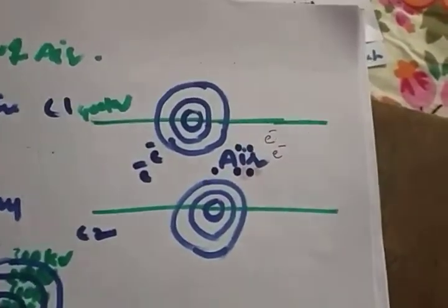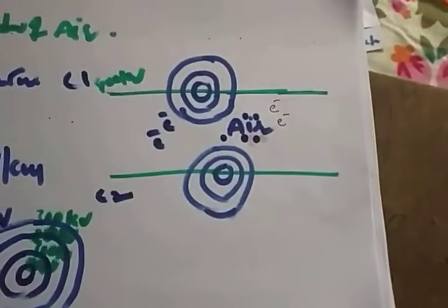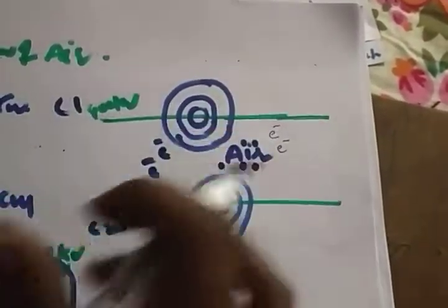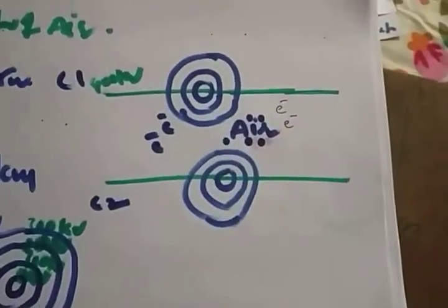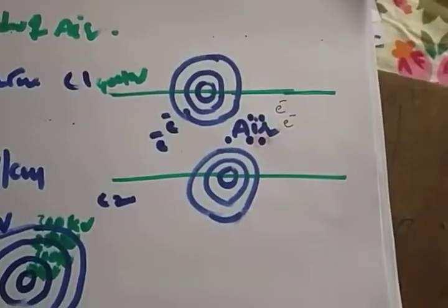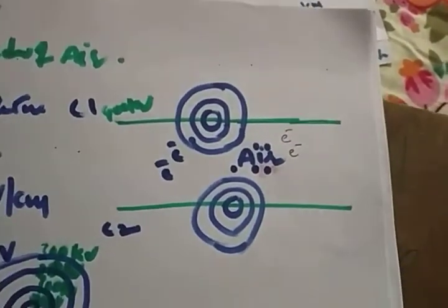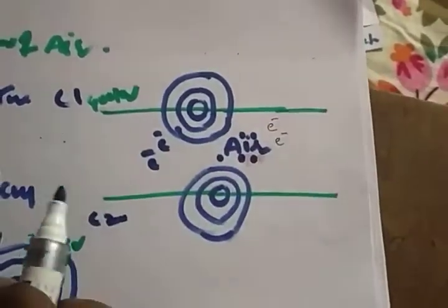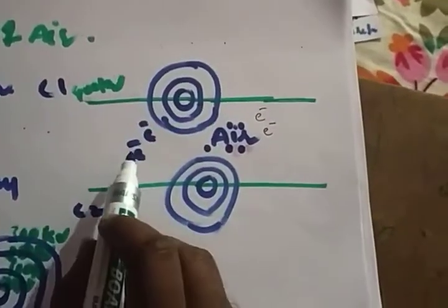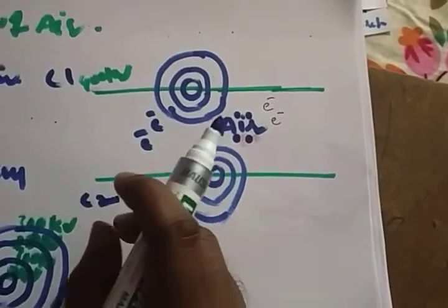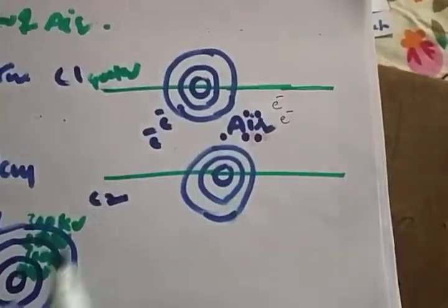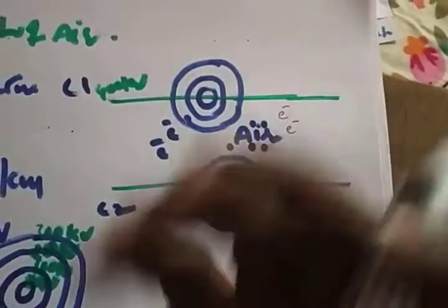Hope it's clear. Now your 400 kV line is passing current, and a potential gradient will be developed, which means the surface of the conductor has the maximum stress. Now initially, the free electrons which exist between the two conductors don't have any velocity.